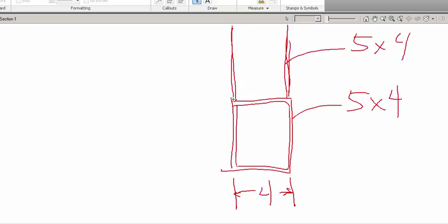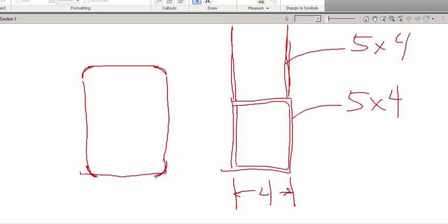But what we find out in fabrication, and you'll see this when you're looking close, is these tubes actually aren't square, they're rounded off. I'm having a hard time drawing this, but where you might think it's squared off, it's actually rounded. There's a fillet on all these tubes. And what happens is you have one tube coming in that's the exact same size, and look what you have right here and here. You have a gap. And what ends up happening is as they try to weld, they end up just burning away this component trying to make the jump. And this is just a fabrication tip.